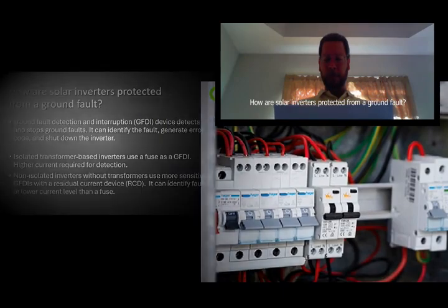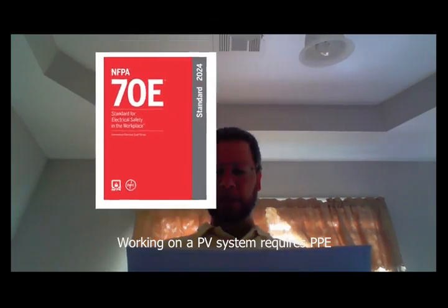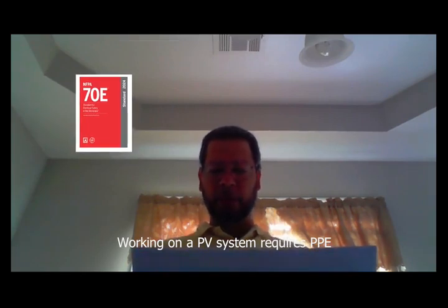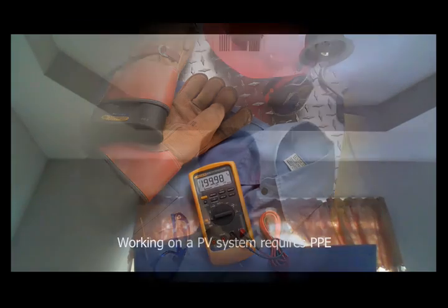Working on a PV system always requires PPE. Anytime you work on an energized system, it is essential that you use the appropriate personal protective equipment, PPE. In the US, the NFPA 70E safety standards guide PPE requirements based on OSHA safety rules and the hazard levels involved. Smaller residential PV systems may only require electrically insulated gloves.